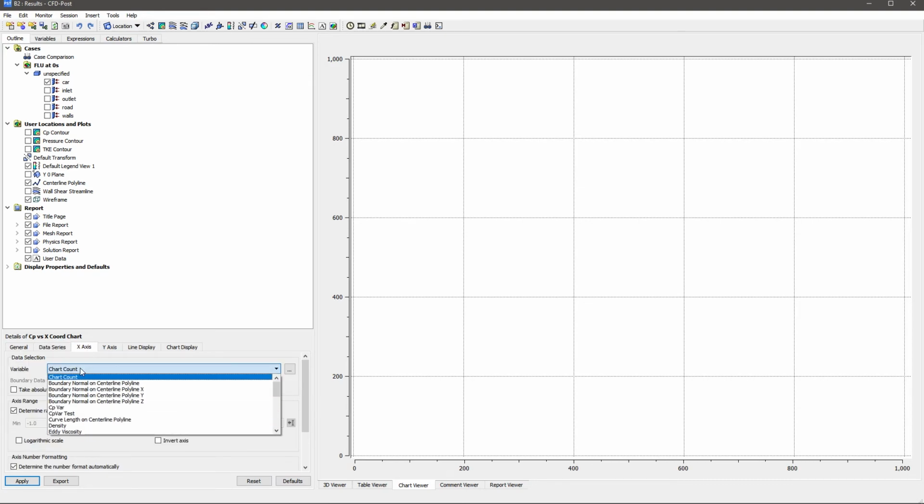For the X axis, we are sampling points and relating them to the X coordinate. So you want to scroll down and click X. You can determine ranges automatically. If ever you have anomalous data and you realize that one point or so may be off with your mesh and the rest of the mesh you've decided is still accurate, then you can adjust the ranges if necessary.